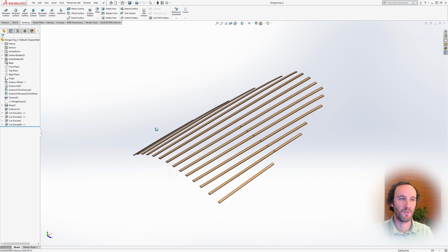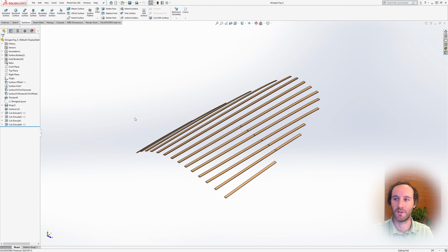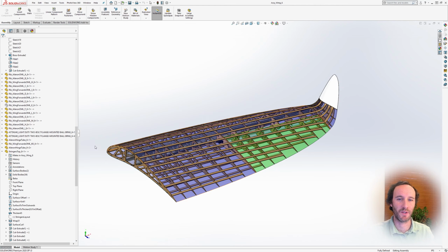In this assembly, I kept the wraps at the bottom level of the top-down assembly. In the higher level assemblies, if you Control Q within that assembly, the wrap doesn't seem to recalculate unless the inputs to it, like the surface or the sketch being wrapped, are changed.